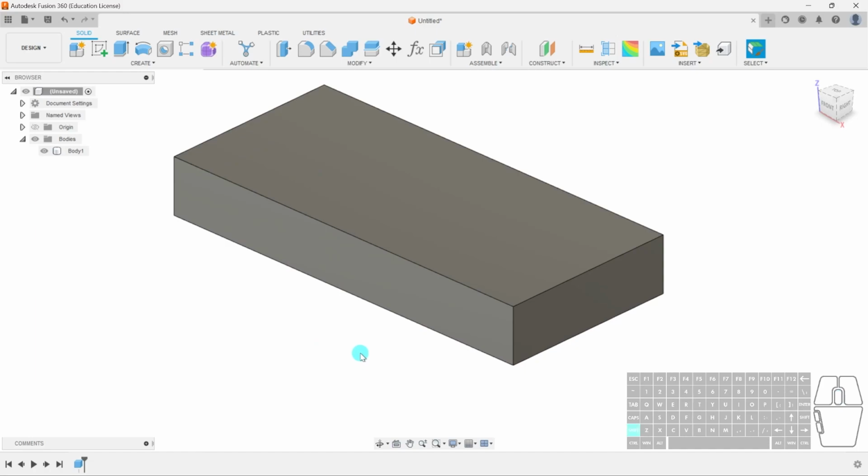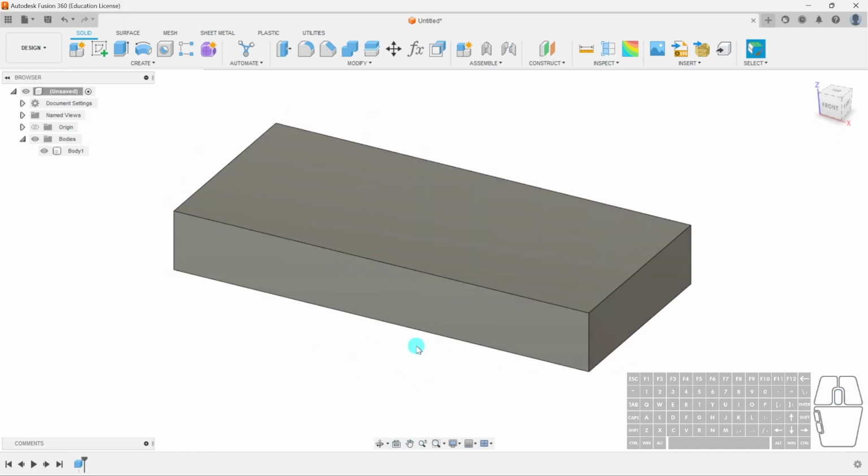Now, the ice cube tray that I'm using is actually dimensioned in inches. So if you remember from our first activity where we made the Lego brick, what can we do to change that? That's right, you can go into document settings, change the active units, and change this to inches. That's right. Welcome to America.